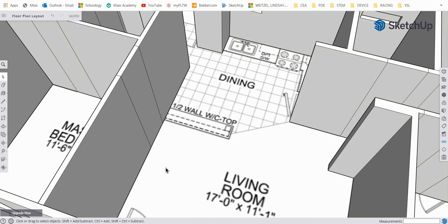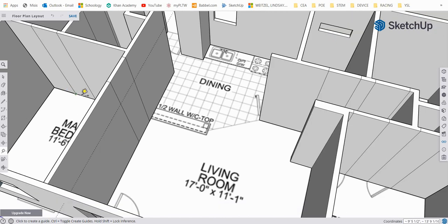All right, the last thing is going to be putting some guidelines at the 7-foot mark, and then cutting the door openings. So we go P, it's up, 7 foot, hit enter, tape measure tool again, up 7 feet, enter. So anywhere we have walls that we need to cut a door into, 7 foot. And then you want to cut your door openings.